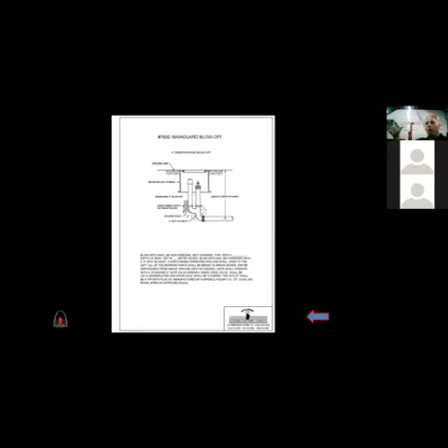When I'm sweeping all of my debris to one area and I'm going to flush it out of a certain hydrant, this would be a great hydrant to use to flush that debris out of the system when you do your unidirectional flushing, because again, the plunger moves up and out of the way, and you can get a lot of debris out of this without damaging your actual hydrant itself like you would a fire hydrant. So we call these the 4-inch hydrants. These are on steroids compared to the 77 and 78. These are the big brothers and sisters that are on steroids because they can flush a lot of water like a fire hydrant for about half the cost.